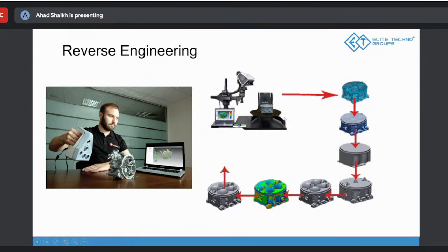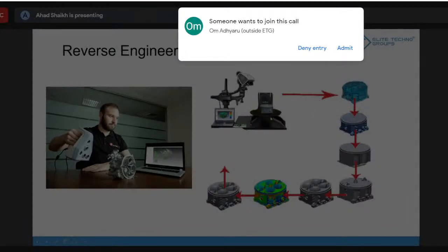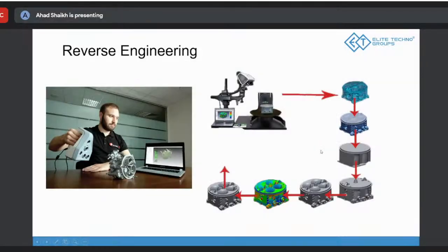And if it does not go well in one go, you have to take multiple rounds of it until you get the complete closed geometry, and you have to mix the mesh, and convert it into the CAD model. So this scanner just gives you the surface geometry, basically, not exactly the solid model, because it doesn't understand how exactly it is made up, and what part of it is solid. So we have to convert that surface geometry into the CAD model, and it happens manually as well.